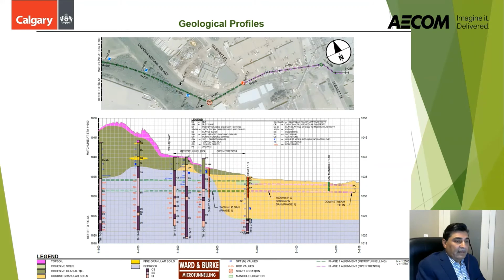And then in the next figure, you can see the tunnel is in bedrock, and then it transitions into coarse granular soil unit. So you see, ground conditions are highly variable, okay, along the tunnel, and each soil and bedrock unit has different characteristics. It is very difficult ground, so we have to provide baselines for those difficult ground conditions. And one thing you should remember, that coarse granular soil unit and groundwater is above tunnel. So you cannot basically do open face tunneling in this soil.